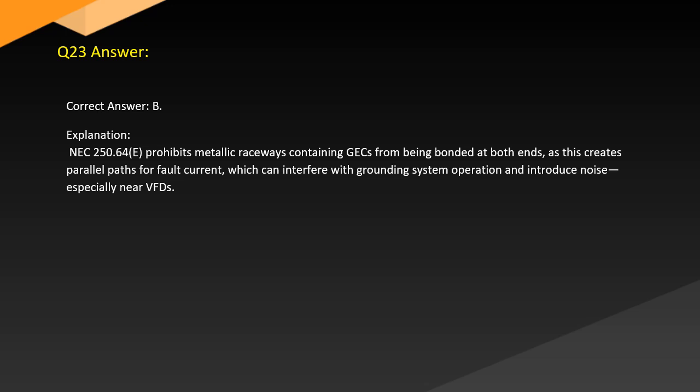Answer. Correct answer: B. Explanation: NEC 250.64(A) prohibits metallic raceways containing GECs from being bonded at both ends, as this creates parallel paths for fault current, which can interfere with grounding system operation and introduce noise, especially in VFDs.